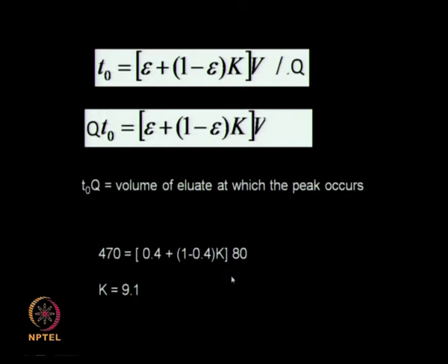So this K is nothing but the linear adsorption isotherm constant, which relates the concentration of the solute in the stationary phase as against the concentration of the solute in the mobile phase. If you remember, q equal to K into C, where q is the concentration of the solute in the stationary phase and C is the concentration of the solute in the mobile phase.